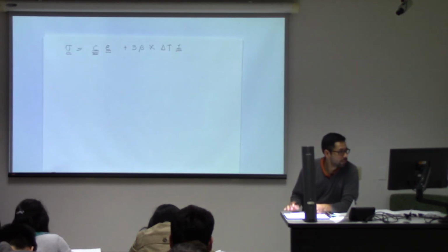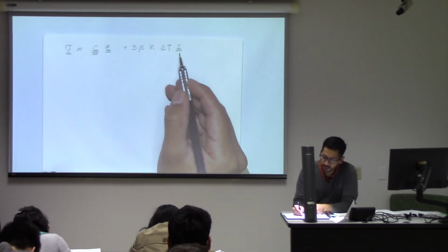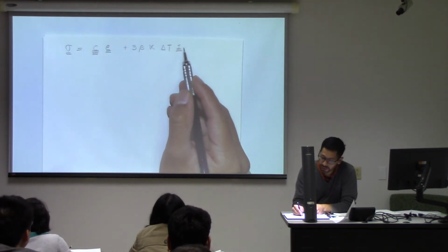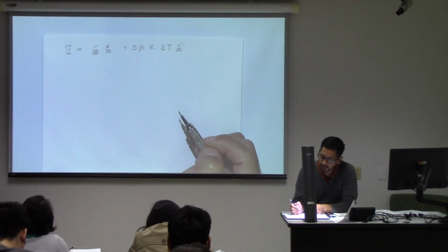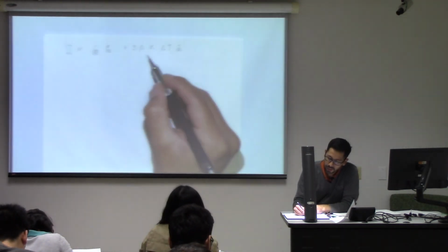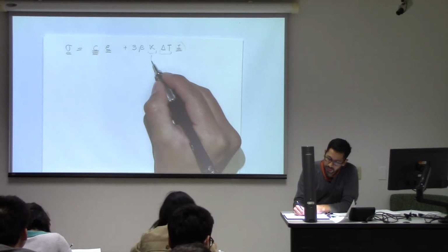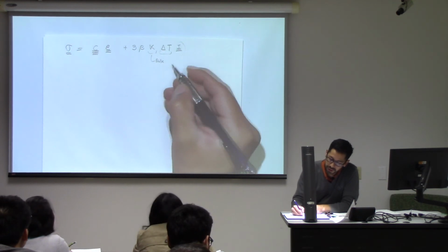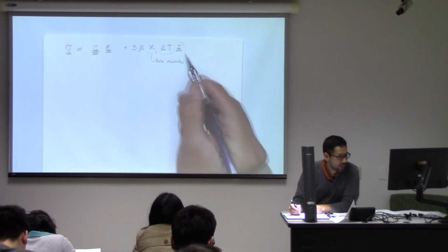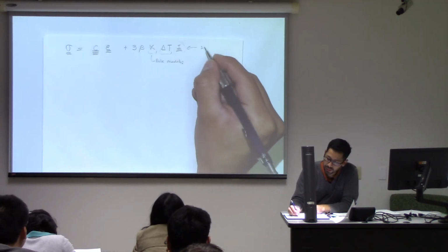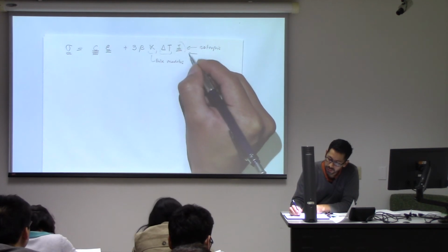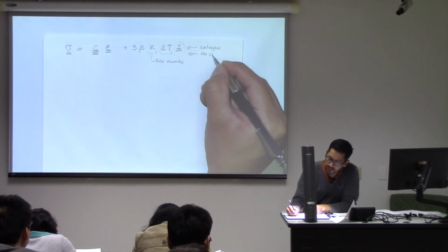Because this is an isotropic rock, we're going to consider that the change is the same in all directions. That's why we have this identity matrix here. This is a change of temperature. Here, this is going to be the bulk modulus. And also, notice this one is invoking two things: isotropic, and also the fact that there are no shear strains.